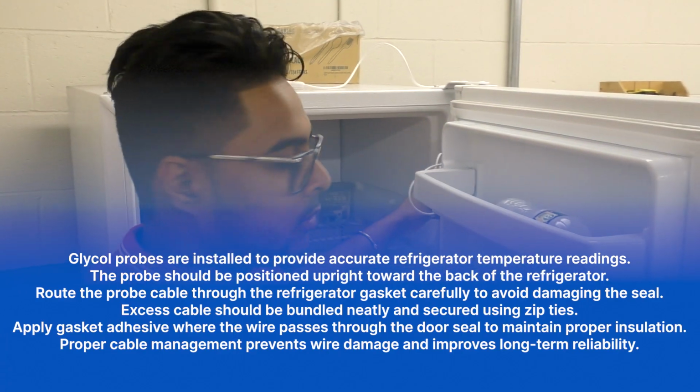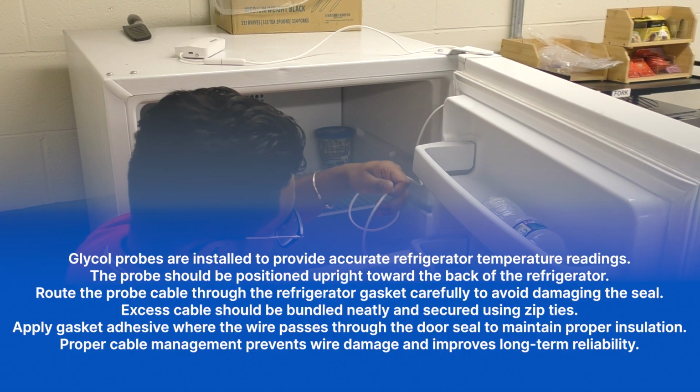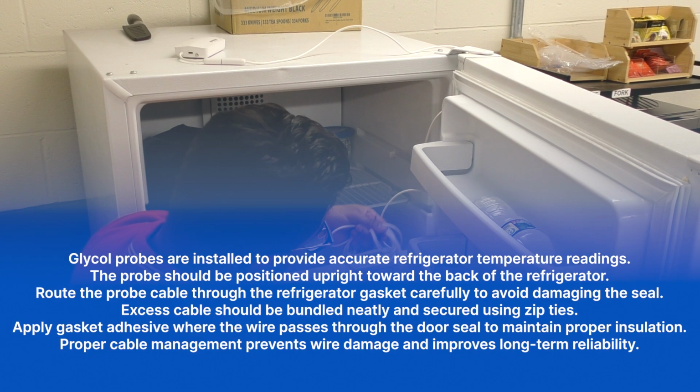Excess cables should be bundled neatly and secured using zip ties. Apply gasket adhesive where the wire passes through the door seal to maintain proper insulation. Proper cable management prevents wire damage and improves long-term reliability.